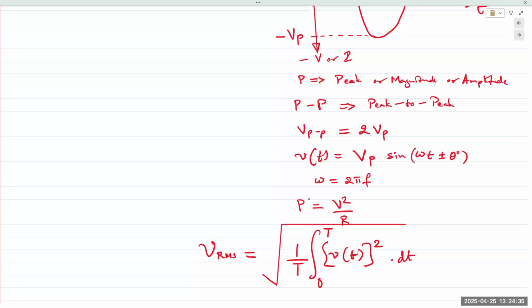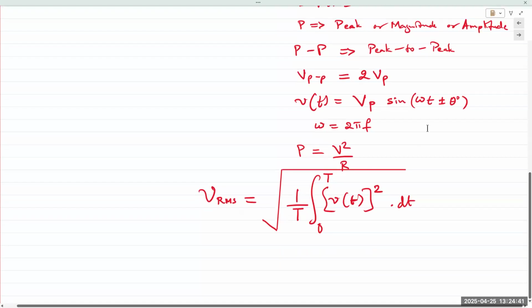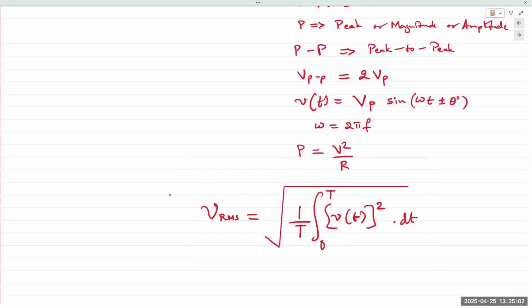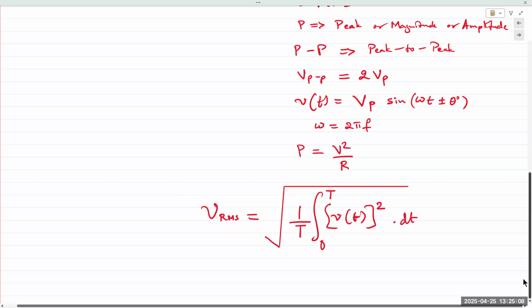Okay. Now this is important for rectifier circuits because in rectifier circuits we have an output that is going to be, let me, then output will have an equivalent DC waveform, sorry, DC value, but the DC value is not the same as the RMS value. Okay. So again, VRMS or IRMS is the root of the mean of the square of the waveform. And for sinusoidal waveforms,